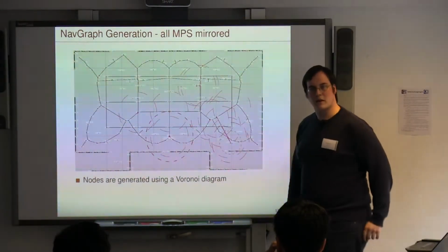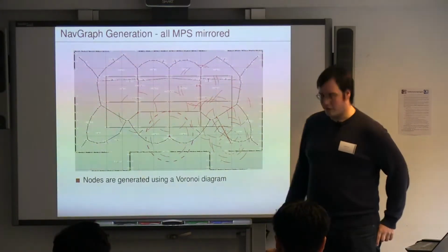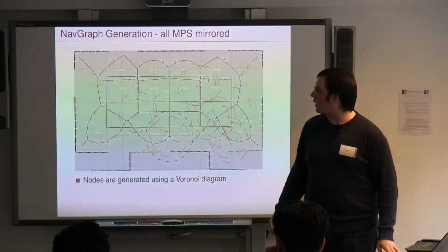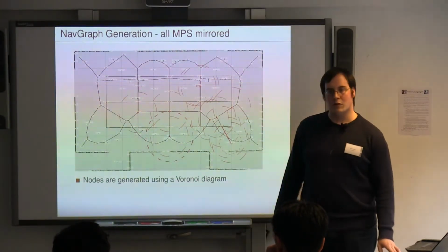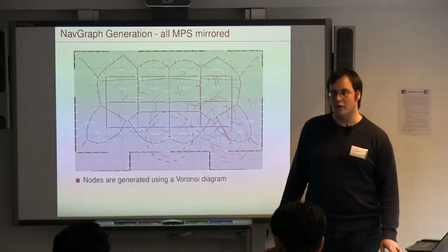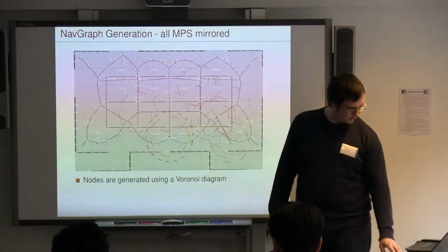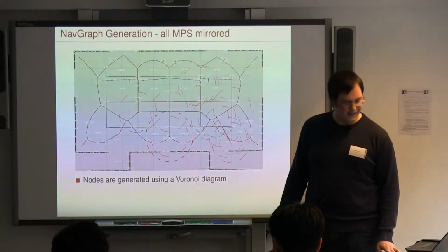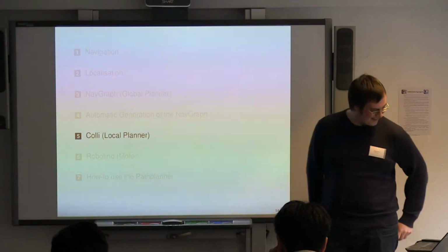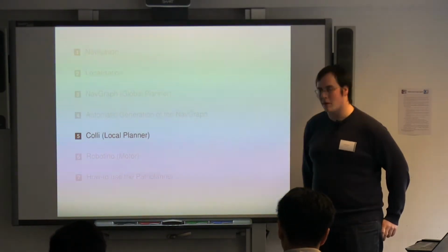And then the next step, where I don't have a picture for, is that the basic graph that we used at the beginning is removed. So we just have the generated path to drive on during the game, which is then hopefully, if we don't make any errors, free of static obstacles. So we just need to care about moving robots of ourselves or the other team or referees, or as in China, security people running over the field. So that's a global planner, or the map-based planner.